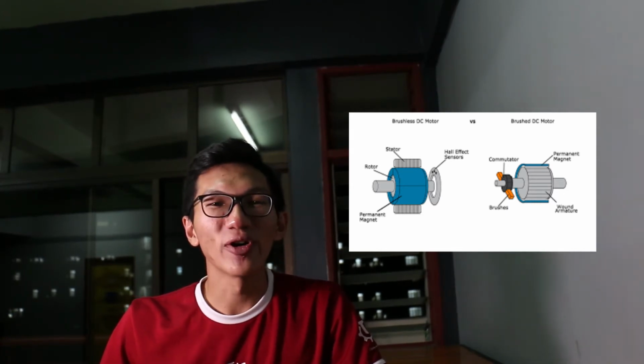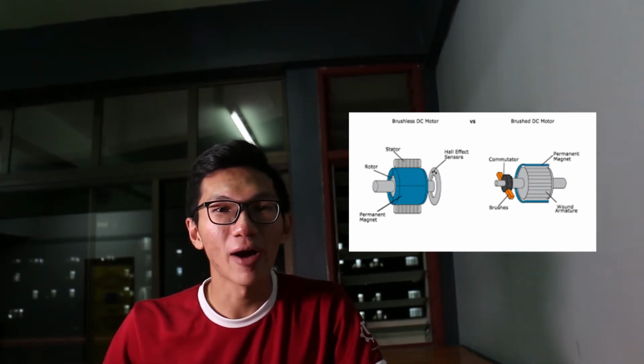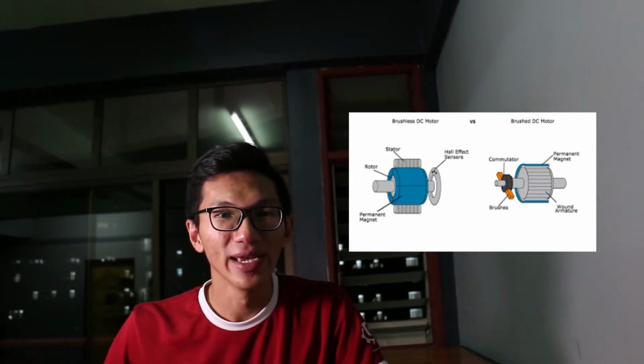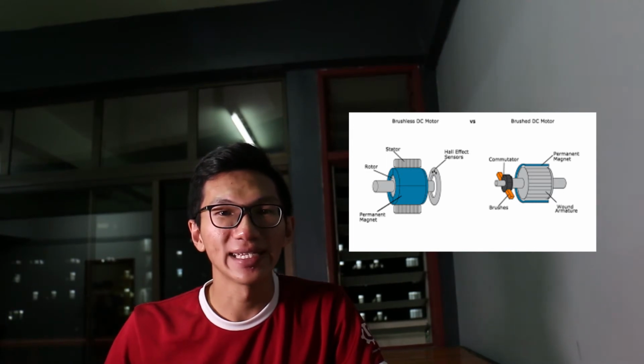A brushless DC motor for the same mechanical output will usually be smaller than the brushed DC motor and way smaller than the AC induction motor. The brushless DC motor is smaller because its body has less heat to dissipate. From that standpoint, brushless DC motors use less raw material to build and are better for the environment.